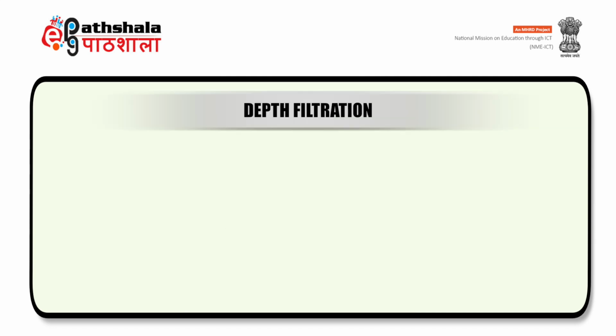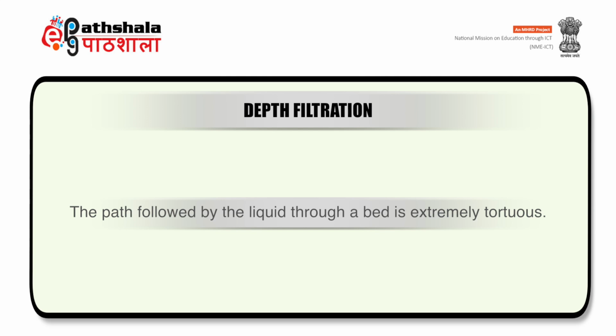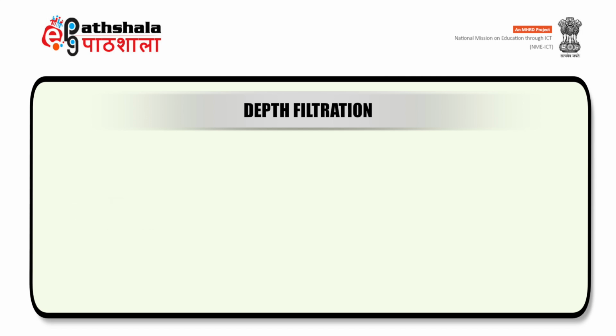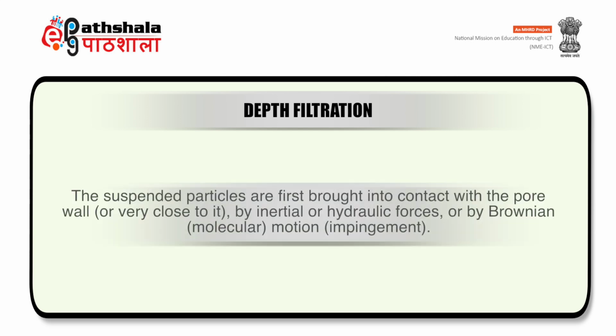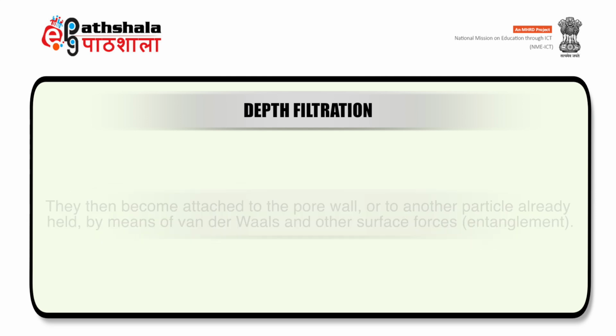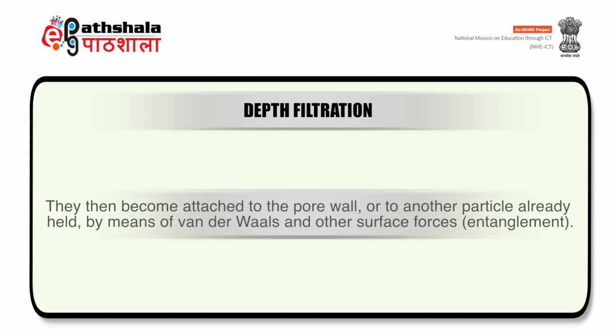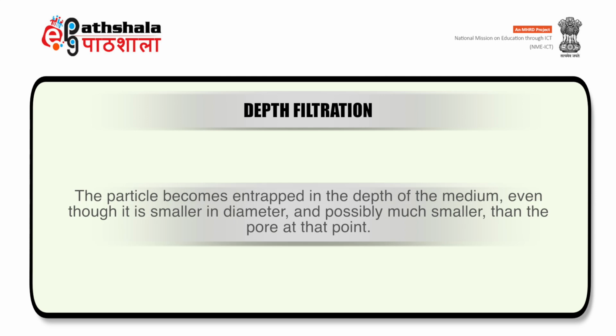The third is depth filtration. The path followed by the liquid through a bed is extremely tortuous. The suspended particles are first brought into contact with the pore wall by inertial or hydraulic forces or by Brownian motion. They then become attached to the pore wall or to another particle already held by means of van der Waals and other forces, that is, entanglement. The particle becomes entrapped in the depth of the medium even though it is smaller in diameter and possibly much smaller than the pore at that point.